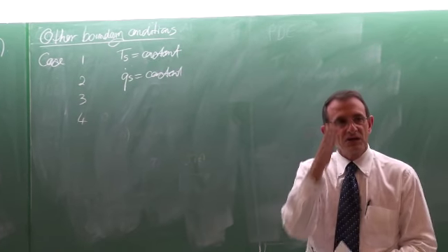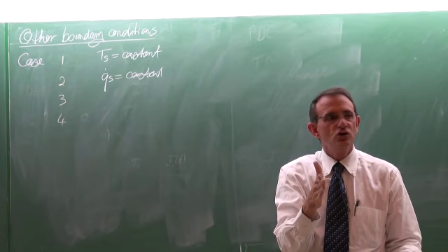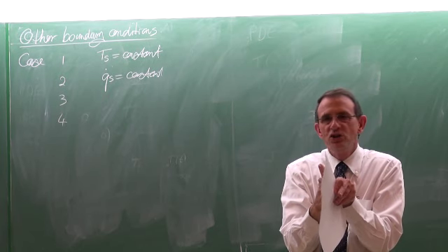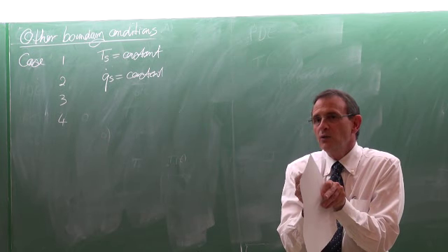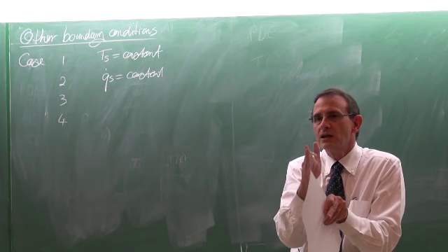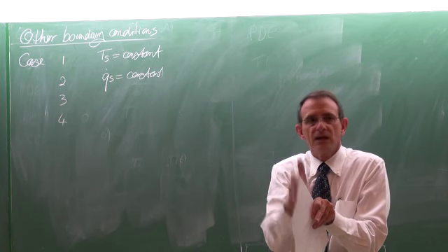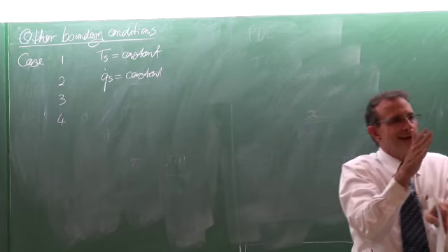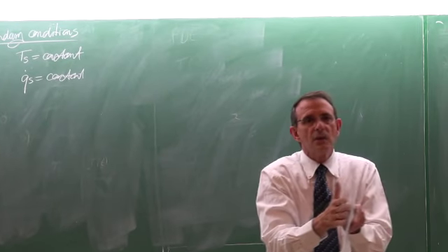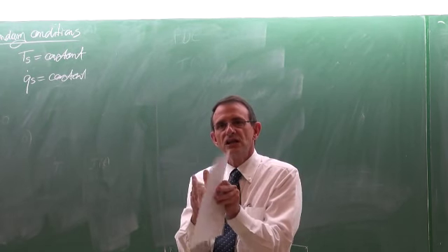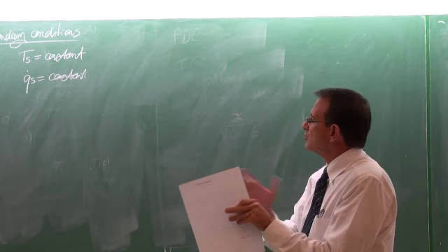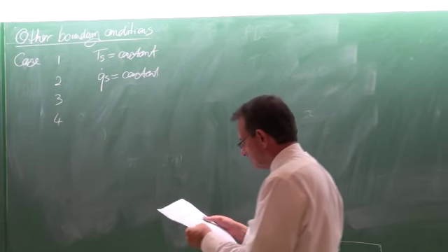So we take the plane wall, we do not change the temperature to Ts, but suddenly we've got a heat flux of maybe 30 kilowatts per square meter. There can be a chemical reaction, there can be an electrical resistance element, something like that. It changes the heat flux to a constant value on the surface. That is the second one.